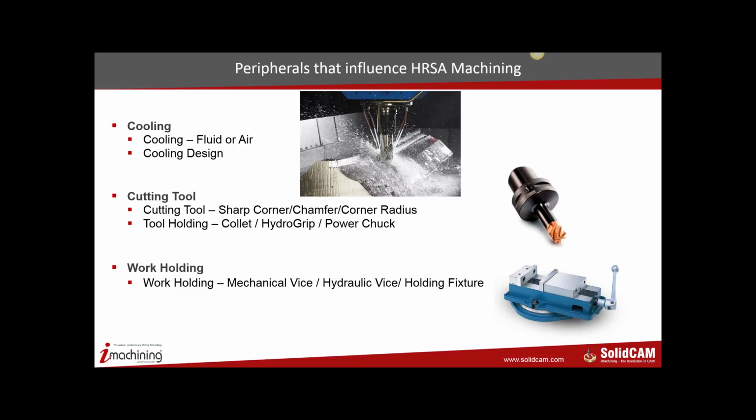The most important, after all, is the work holding. How do you hold your work? Mechanical-wise, hydraulic-wise, holding fixture. So again, this depends on the part, this depends on the design. Because in some cases, you cannot hold a part in a vise. You need to have holding fixtures for it. So the design of the fixture becomes very crucial.